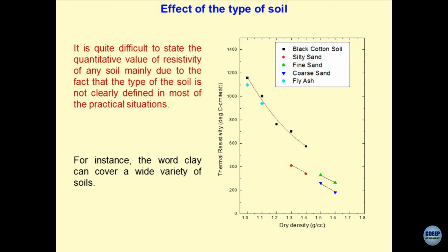So, this answers the question you were asking, that fine grained materials, because of the clay minerals, are highly resistive for the same density. Another question to complicate this statement would be, clays cannot be compacted. Your hunch was that you will compact something and create a barrier system. Now, this becomes a very interesting and complicated problem. If you are dealing with clay minerals, how would you compact them to a certain density? That itself is a big engineering task.